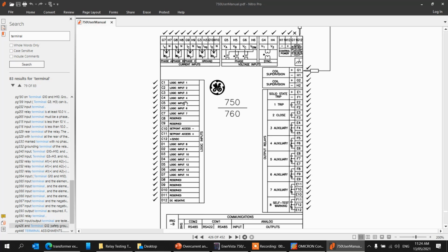Normally, the intertrip is from downstream to upstream. So you have to check the schematic. If no schematic, go to that specific model and look at which terminals already have a wiring connection at the back. If all are normally open, when you pull that out, still normally open. But if that contact is normally closed and you pull that auxiliary relay out, that normally closed contact will become normally open. It will trigger other stuff out there. So it's not straightforward.